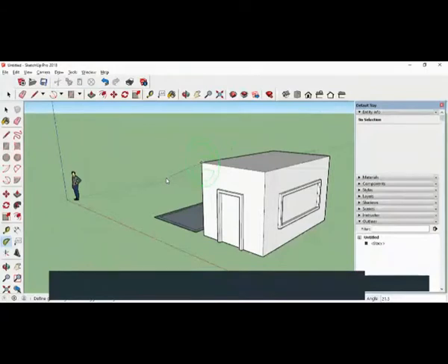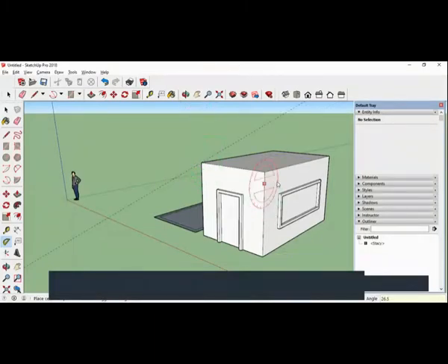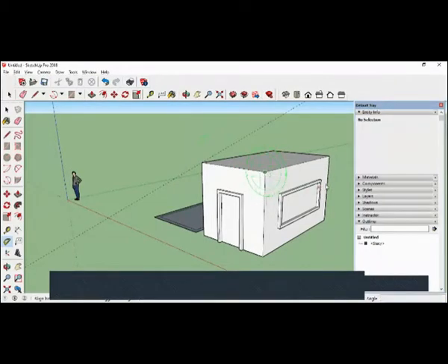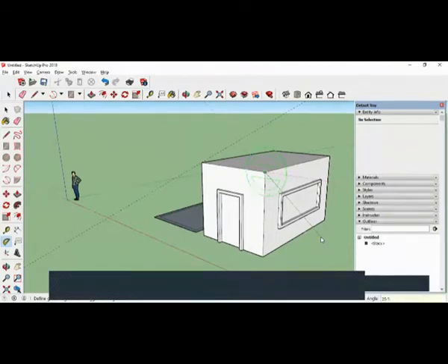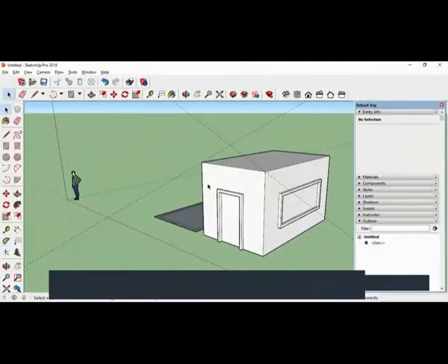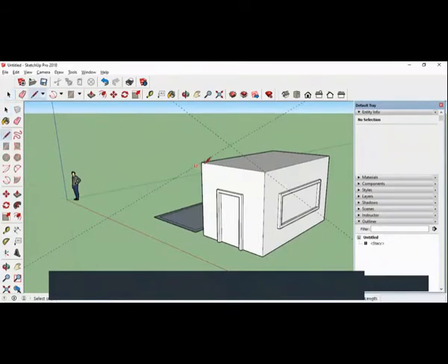Okay, usually what we do is we give 26.5, which is the standard slope used. So you just type 26.5, enter. So we got the slope here. Now I want to get the slope from here. So I'll come here, click here, drag like this, click, drag like this, again 26.5, click. So you got the sloped line. We got the slope line. Now I will use the line command L, draw from here, here, here. So immediately a face was created there.